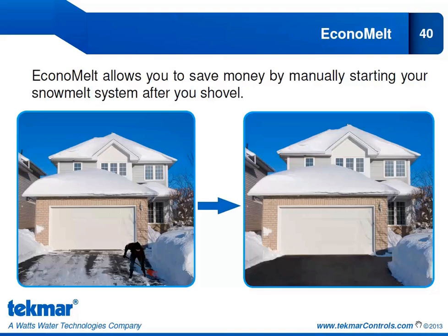So you'll still be using your sensor to provide that automatic stop when the sensor is dry and the add melt time has expired. Advantages to that are the system does not stay on for longer than it has to. It's not stopping too early, but it gives you some control over your operational costs by providing that option of shoveling before you start your snowmelt system.